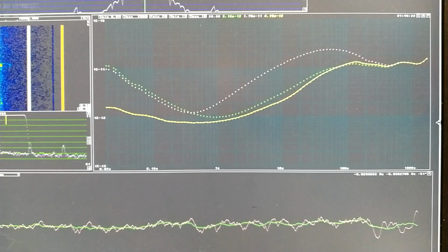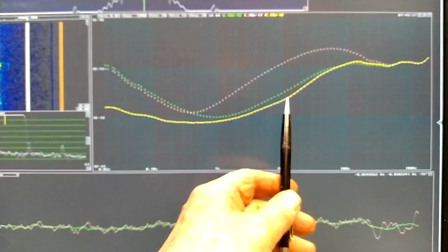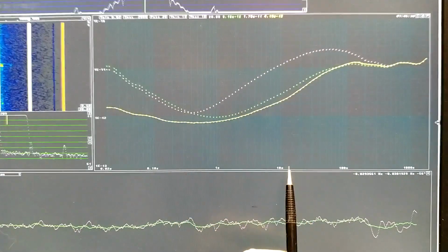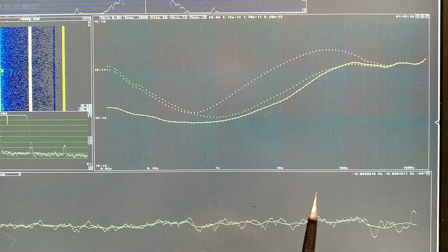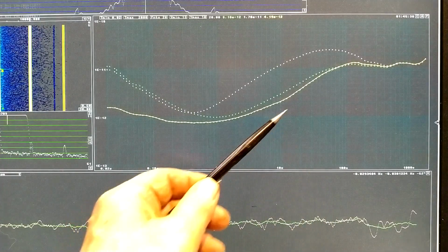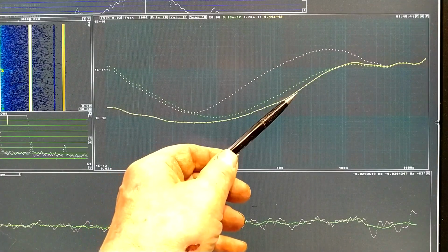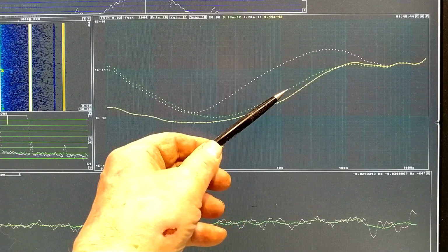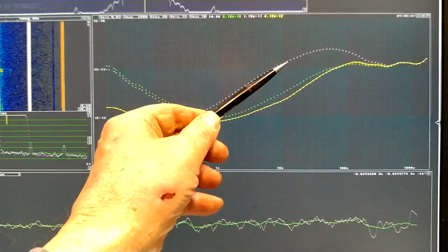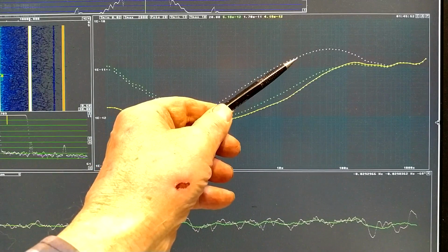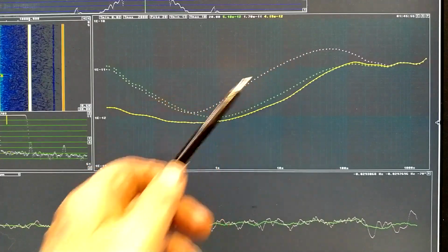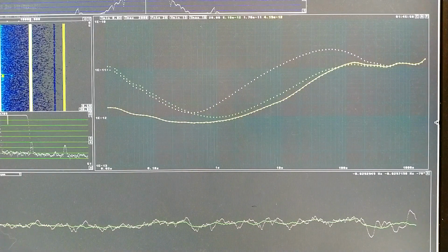Here is what I see in Linrad. I can trust results up to about here, because up to 20 seconds, maybe 30, I can trust the correlation. I don't know whether it has been running long enough, but the correlated spectrum is a little bit below the result for channel 1. And channel 2, which has a not quite as good oscillator, the evaluation gives a much higher value for the Allan deviation. Anyway, I can take notes.